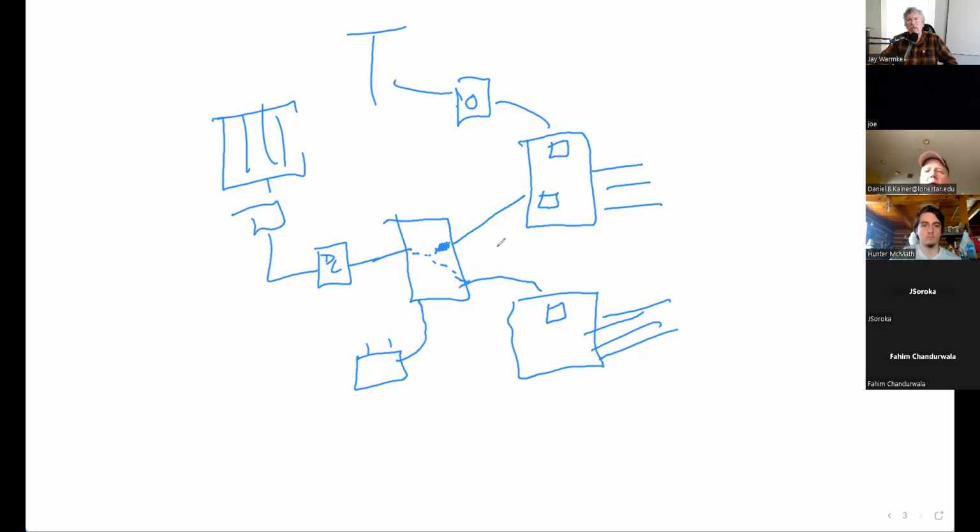And the array will service this. If it needs power, it'll pull some from the battery. So the battery will act like the grid now as a backup. If I have more power than I need, the array is going to fill up the battery. If the battery's full and the loads are being serviced by the array, well, then it just stops producing because there's no load for it to go to.